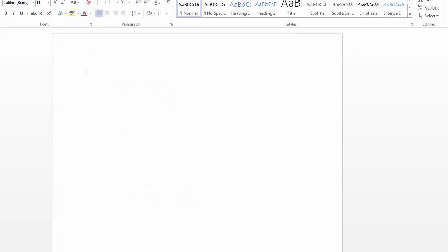So we assign node 1, node 2, and node 3, these 3 junctions. The first step is to assign the reference node and V1, V2, and the remaining nodes. For step 2, we apply KCL.